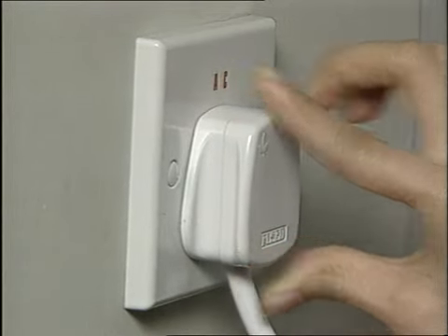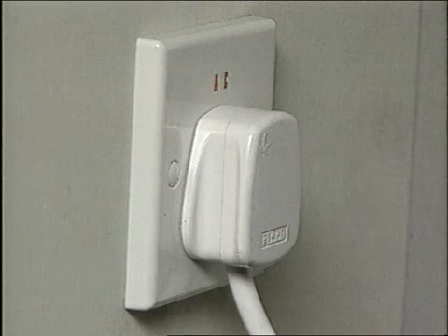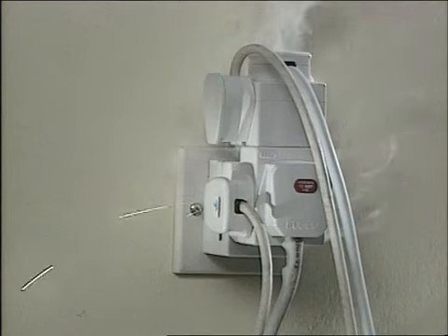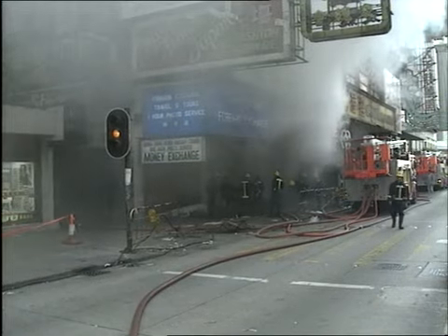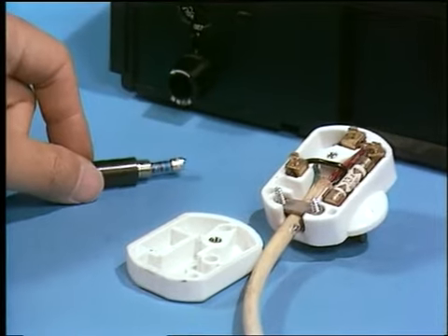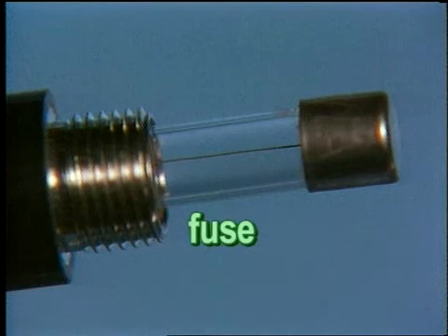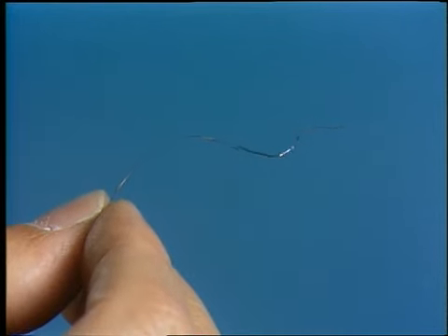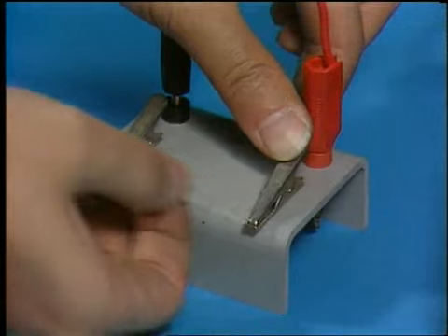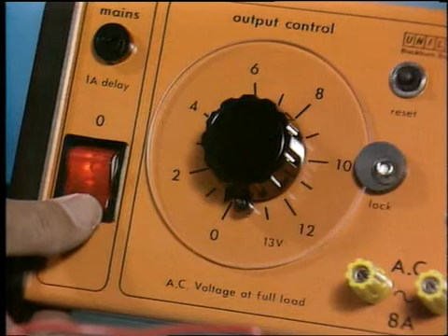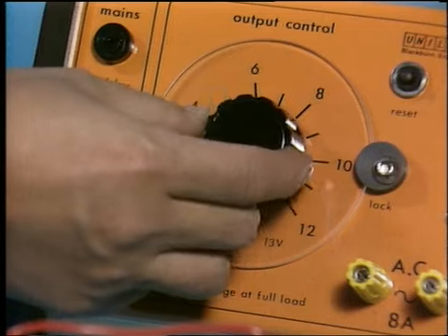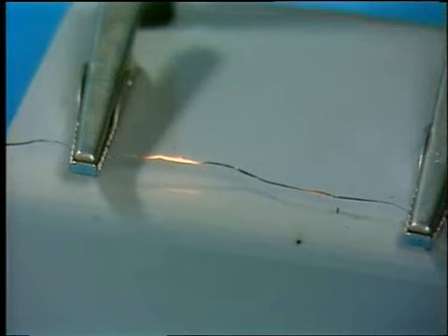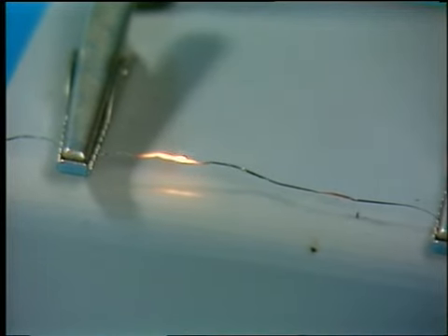Moreover, in order to protect the electrical appliances from damage and to prevent potential fire hazards due to overloading, fuses are installed in many appliances and the circuit boards at home. A fuse installed in an electrical appliance is a piece of metallic wire of a low melting point, which allows only a limited amount of current to flow through. A sudden influx of current over the limit results in a rapid rise in the temperature of the fuse wire. The wire then burns and the current is cut off.